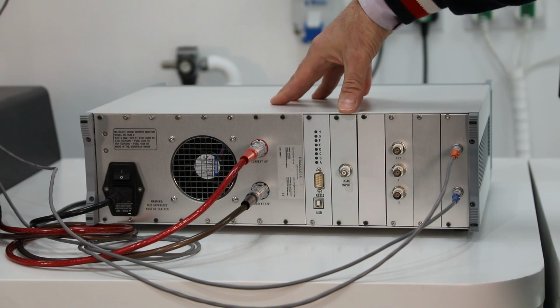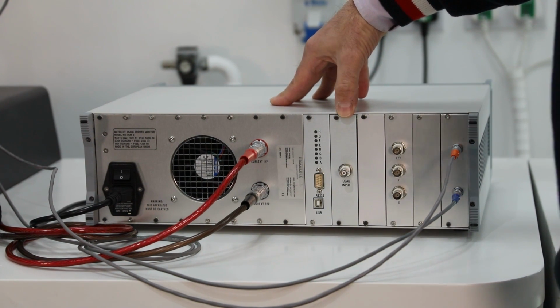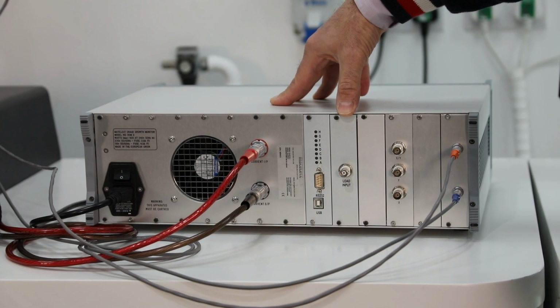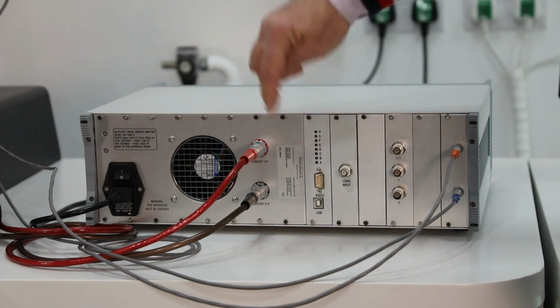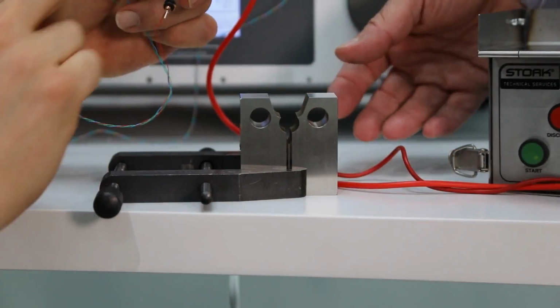There is the load cycle, which you mentioned that some people would like to synchronize to the load waveform. You can do that by finding that coming out of your Instron and plugging it in at that point, and we can synchronize to many different types of waveforms and take a reading at peak or indeed at the trough or at the crossover point.